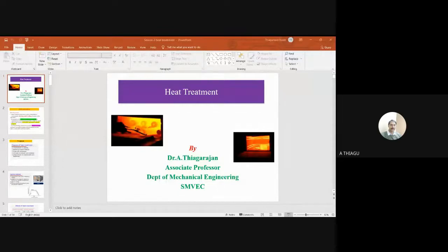So what is the purpose of annealing, or what are the things we can achieve? You are able to relieve the internal stress. You can increase the softness, ductility and toughness. These properties can be achieved by means of the annealing process, and a specific microstructure modification is possible, because most of the grain modification happens by means of the slow cooling process only.